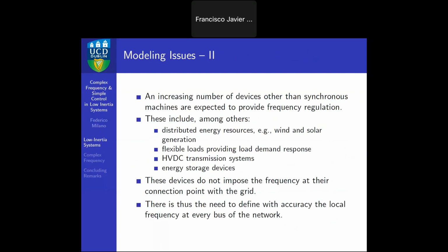The problem is also that we don't have only synchronous machines. If we had only synchronous machines, we would immediately have the answer, because it would be the rotor angular speed. There are easy ways to calculate the frequency then: we can just take the omegas of the machines and do some kind of interpolation. That would be what we call the frequency divider. So that was an immediate calculation to do.